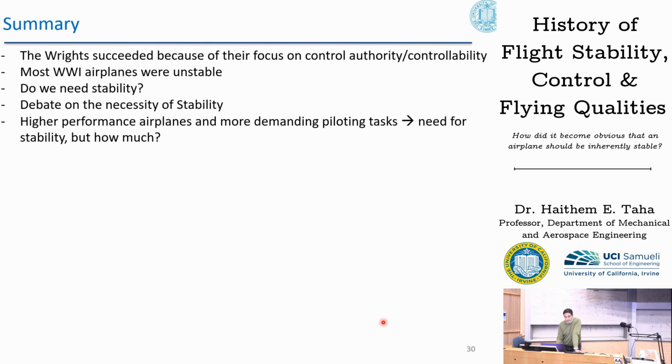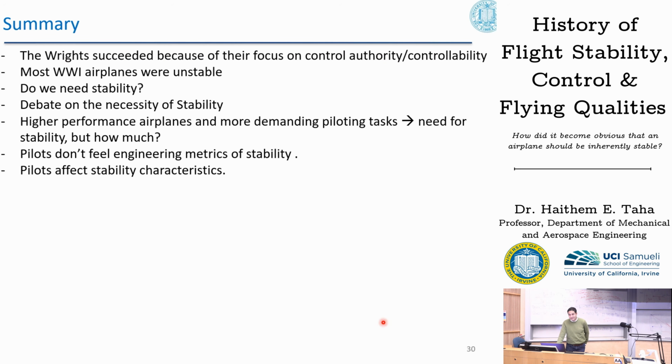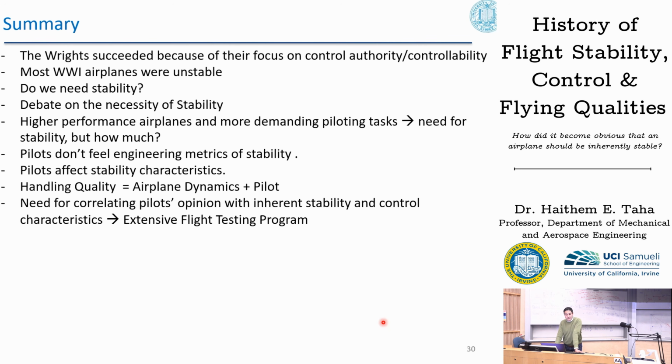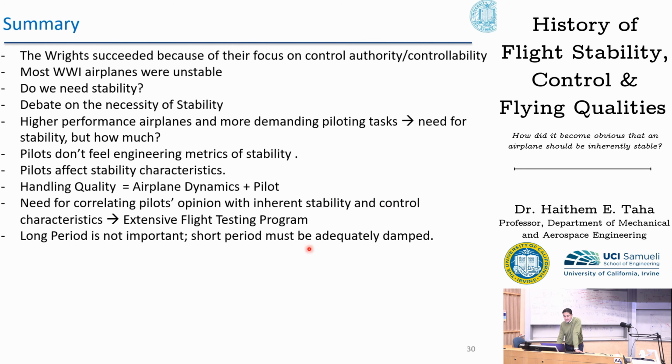But the question was how much? And the main challenge was that pilots do not feel the engineering metrics of stability in flight. In fact, pilots affect stability characteristics. So indeed, handling quality of the airplane is about the interaction between airplane dynamics and pilot. This urged the need for correlating pilot's opinion with stability and control characteristics, which required an extensive flight testing program. Many lessons came out, one of which was that the long period mode is not important, and the short period mode is the important one that must be adequately damped.